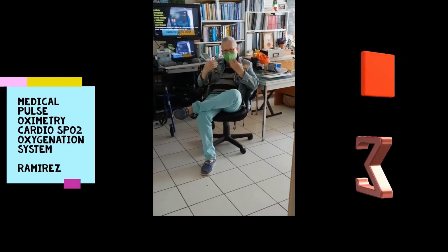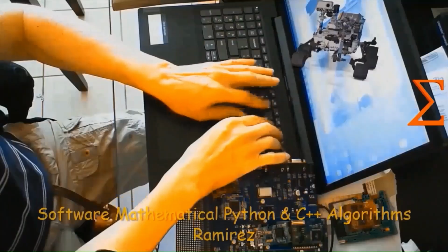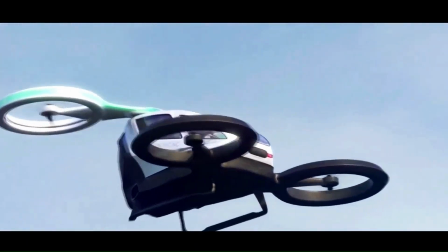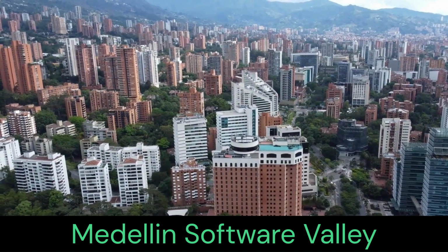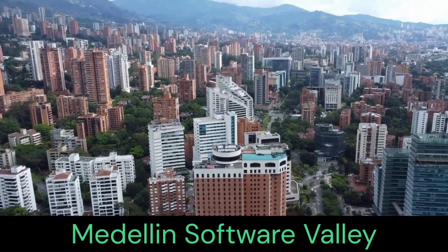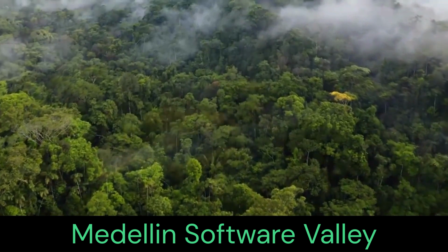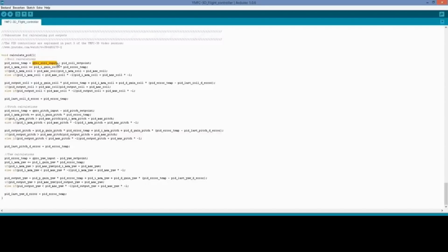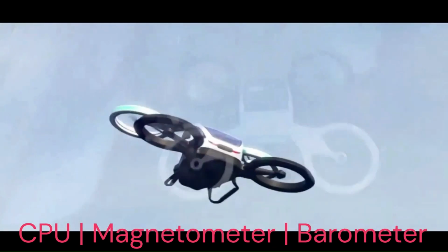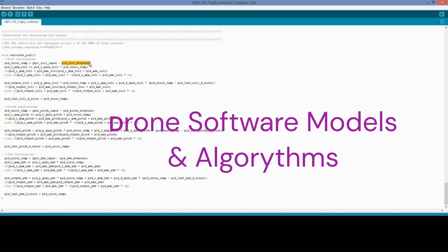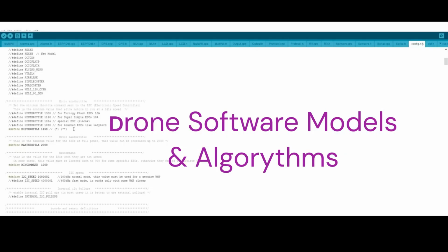The motors should rotate anti-clockwise to counteract the torque of the propellers. All the propellers will generate the necessary thrust for the intelligent drone, making sure there are corresponding clockwise and anti-clockwise rotating pairs of propellers. For instance, for lifting more weight, use a large diameter and pitch propeller.